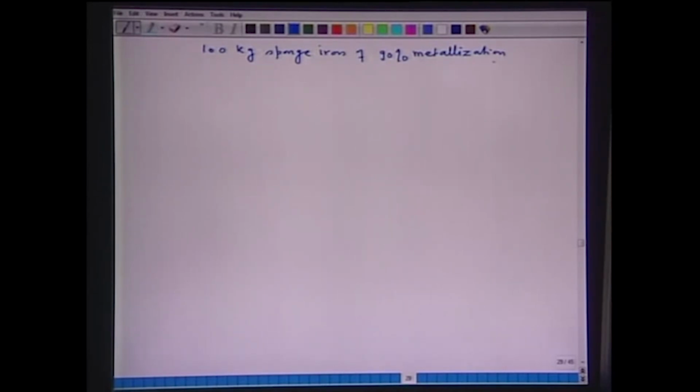Now, just a background calculation, you require around 132 kg of iron ore of 80% Fe2O3 and 20% gangue. So, if you want to calculate the effect of changing the proportion of DRI in the feed on free iron, Fe as FeO and the gangue, then you have to perform the calculation by considering how much iron ore is required, how much iron it has and how much gangue it has. I have done this calculation and I am presenting it here.